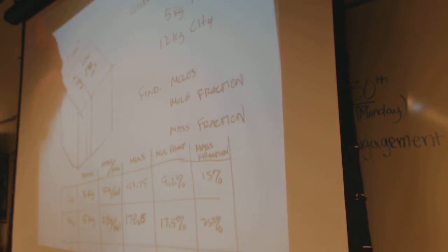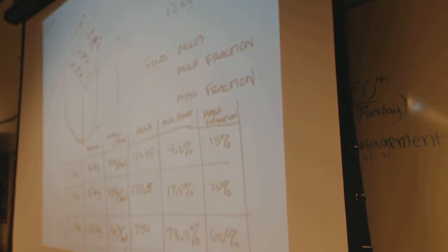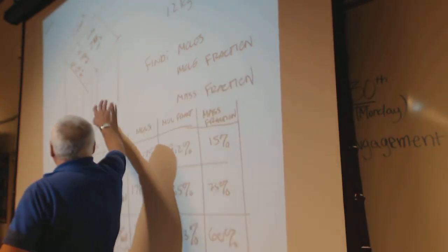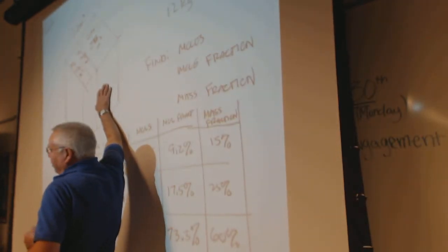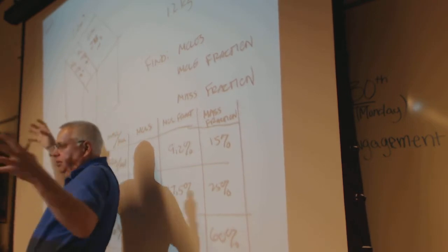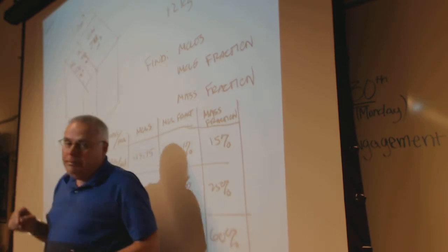And what would be left was all of the N2, and it would be 0.175 meters cubed, if you could separate them like that. So they could either have the partial volume at that pressure, or you can have a partial pressure at the whole volume. Because if this was all at 100 kilopascals,